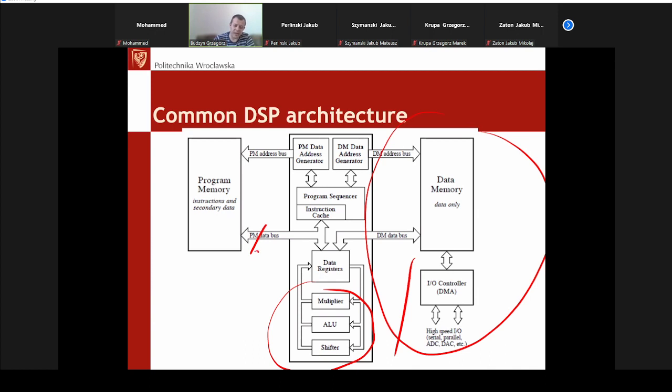The idea is to have here, for example, a 256-bit wide bus, and in order to speed up the access, read the instructions from the program memory. In other words, we read a couple of instructions in one reading cycle, reducing the need for the instruction cache and/or reducing the latency in accessing the program memory. That's very long instruction word.